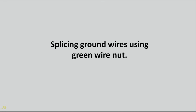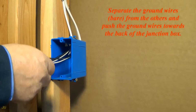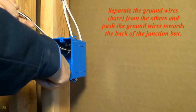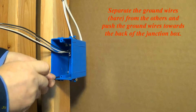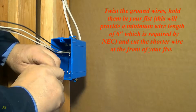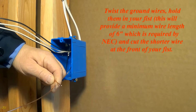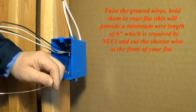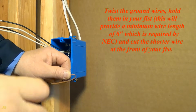Splicing ground wires using green wire nut. Separate the ground wires, bare, from the others and push the ground wires towards the back of the junction box. Twist the ground wires. Hold them in your fist. This will provide a minimum wire length of 6 inches, which is required by NEC, and cut the shorter wire at the front of your fist.